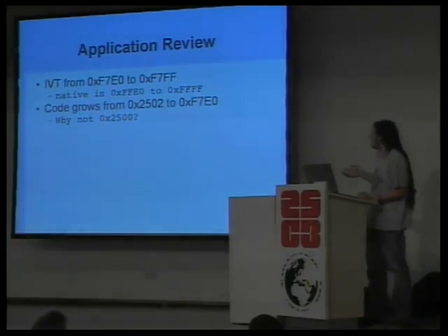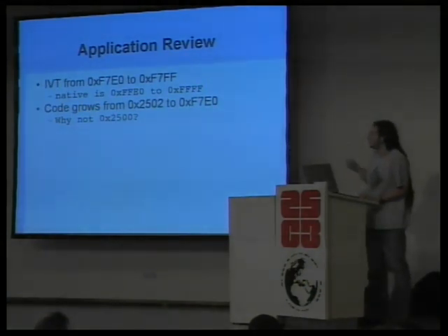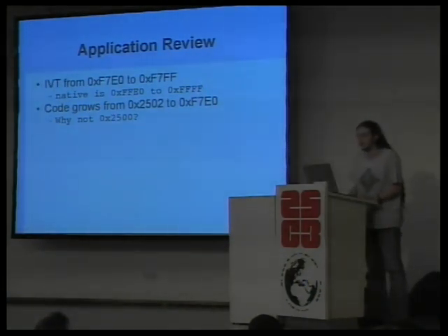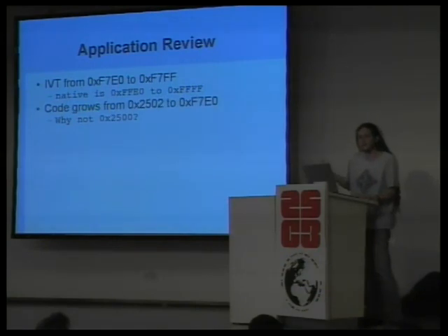The infuriating thing about this, and what took me a week to notice, was that the reset vector is not among those that is proxied. And while flash memory begins at 2500 hex, this is where the chip begins to execute after it exits the bootloader.